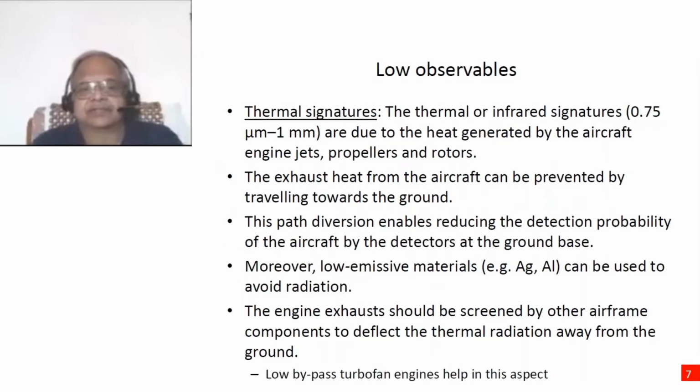Thermal signatures, or infrared signatures, vary from 0.7 micrometers to 1 millimeter due to the heat generated by the aircraft engine jets, propellers, and rotors. And of course, the exhaust heat from the aircraft is the largest source of infrared signature, and can be, of course, sometimes if you are being chased by a missile, if the engine exhaust engine can be kind of hidden